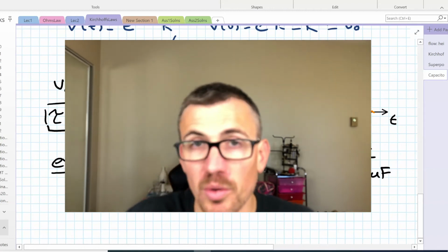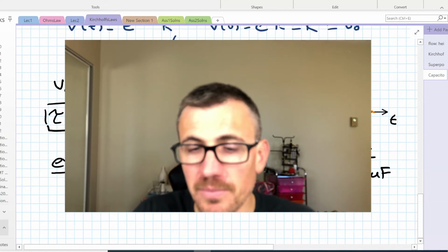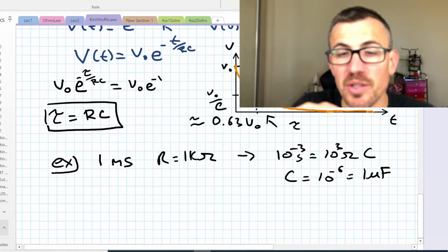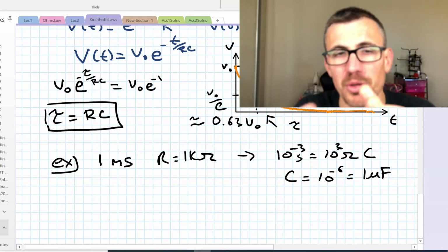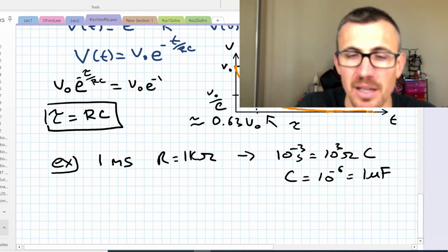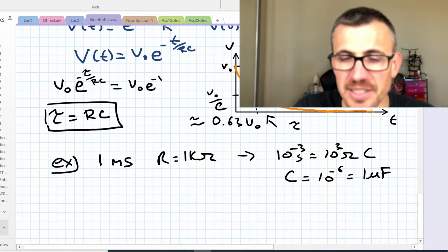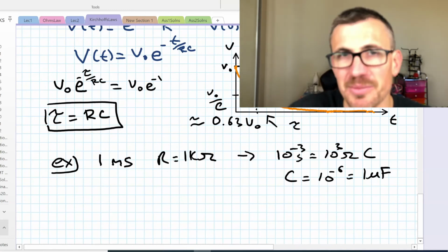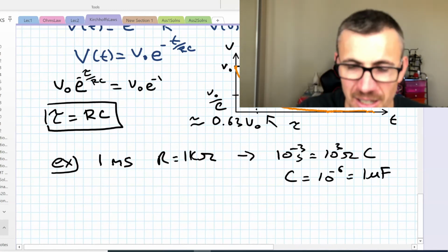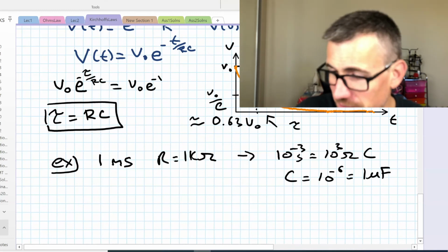Some of these electrolytic ones, and the super capacitor included, are polarized. That means you have to put them in a certain way, because the way they work, there's an oxide layer that builds up when you put the voltage a certain way that forms part of that capacitive barrier. Let's plug, maybe not the supercapacitor because I'm too terrified, something like this in the wrong way and see what happens. I have a 10 microfarad capacitor here rated for 63 volts. We will put 63 volts across it, but we'll violate the polarity. We'll see if anything exciting happens.